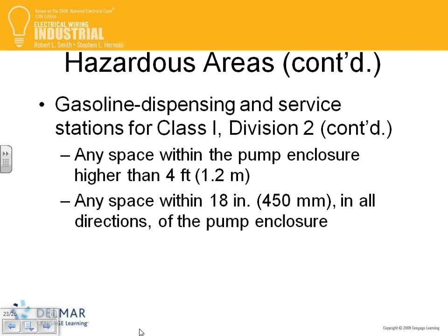So there's a few, I think, any space within the pump enclosure higher than 4 feet. I don't know if I have the picture here, that 18 inches around here. No, I have the picture. You guys have the picture in your book. If you look at page 262, it's a nicer picture than I have. There's a gas station, 4 feet off the ground, and 18 inches around the pump itself is a class 1 div 2.